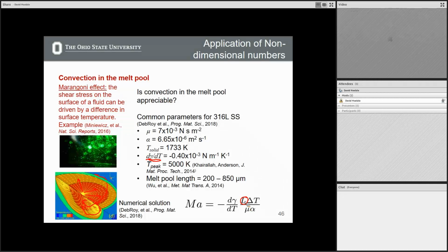So we can then plug this into the Marangoni number to see, and just a reminder, the Marangoni number is the ratio of surface tension driven forces to viscous forces, right? So just to give you intuition on this. If we have a very strong surface tension force, there's a strong driver for material to flow. While alternatively, if there's a very strong viscosity in the fluid, that's going to be resistance to flow, right? So it's looking at the balance of these two forces and turning it into a ratio. That's the idea that we have the Marangoni number.